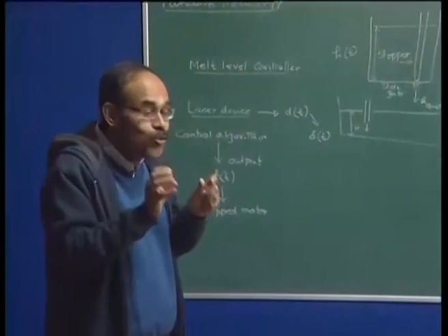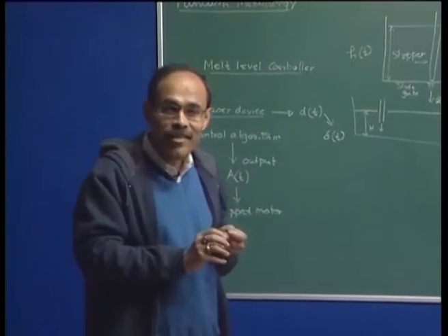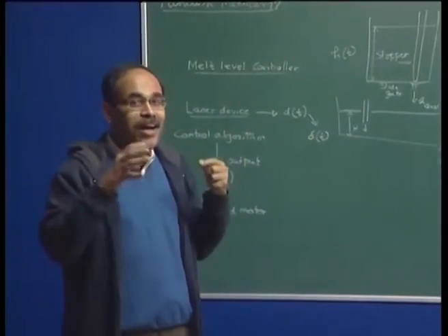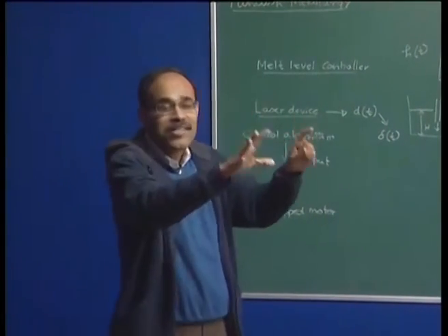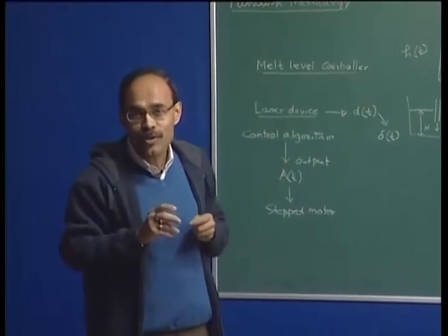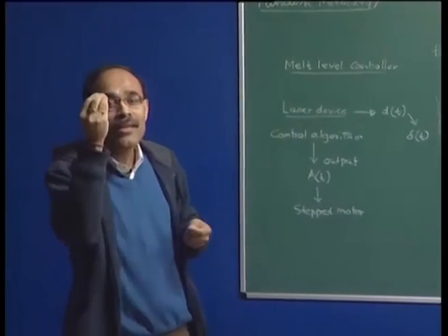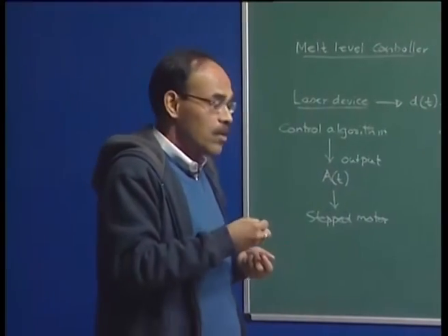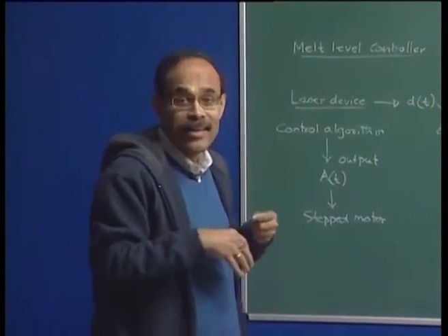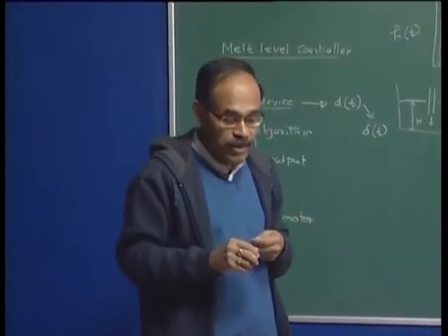And in the conclusion part of this lecture, I have tried to show you how the melt level is controlled through slide gates or stopper rod by using a simple control algorithm and a sensor, and this gives you an idea about the simple process control which is available there. Nobody has to do anything, there are computers, there are sensors available, and it is being done absolutely automatically. Okay, no manpower is needed, and this gives you some flavor of perhaps the simplest example of dynamic process control in terms of the melt level control in tun dish and ladle that I have discussed. So, now I am going to move on to the next topic.